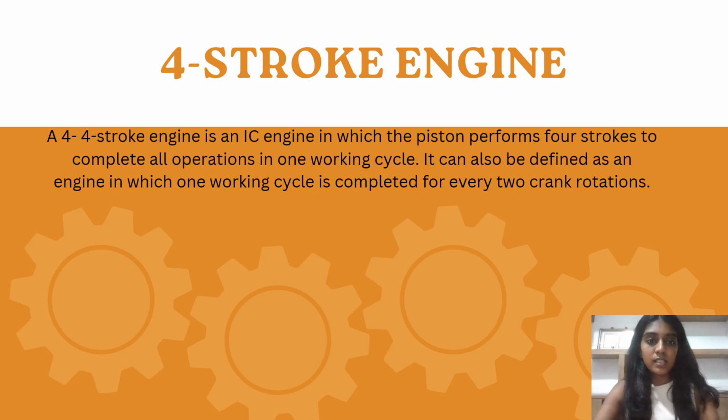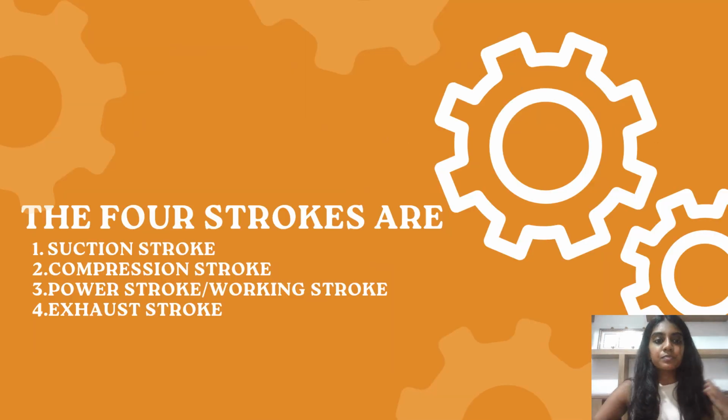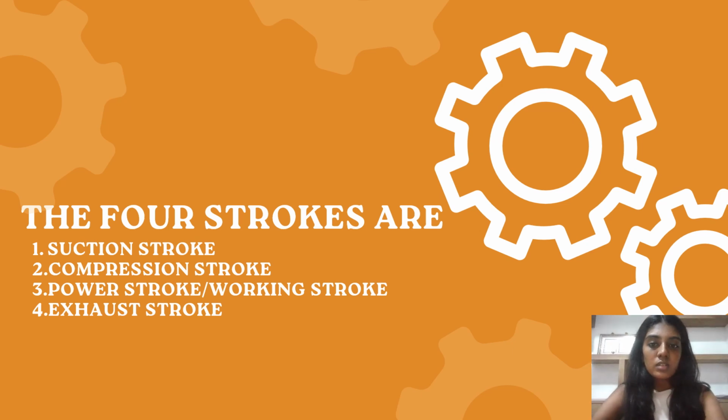A four-stroke engine is an IC engine in which the piston performs four strokes to complete all the operations in one working cycle. It can also be defined as an engine in which the working cycle is completed for every two crank rotations. The four strokes which are performed in this type of engine are the suction stroke, compression stroke, power stroke or working stroke, and the exhaust stroke.